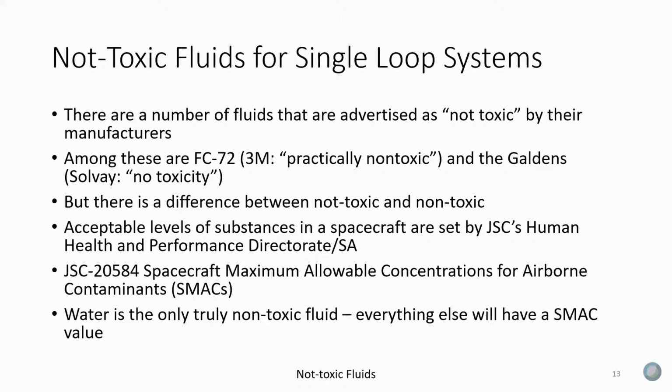So if you get to a point where you get stagnation in the radiator and flow through a tube stops in a deep space environment, it's going to freeze. And once you freeze, you can't get it back just by getting flow back. You've got to do something to physically thaw it, whether it's heaters on the backside or a heat leak from an adjacent tube. So it gets a lot more tricky than what they did in Apollo.